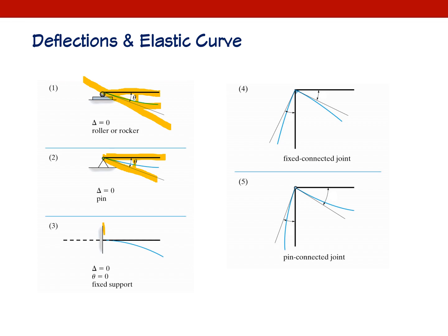How about a fixed support? If you recall from starting statics, I asked you to view the cantilever as extended into and behind the support location, so that because of that continuity, there will not be any deflection angle there. In this case, the deflection angle will be 0 for a fixed support.